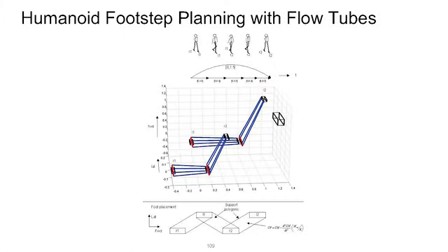Okay. So one example is humanoid footstep planning. So this takes a complex system. You have a bunch of different parts of the system. You have your center of mass dynamics, you have your leg dynamics, foot dynamics, and so what you're trying to do here is plan your footsteps forward and through time. So you have your original plan of where you want your footsteps to be for different parts. So there's discrete things that happen in the system as we previously seen in the lecture.